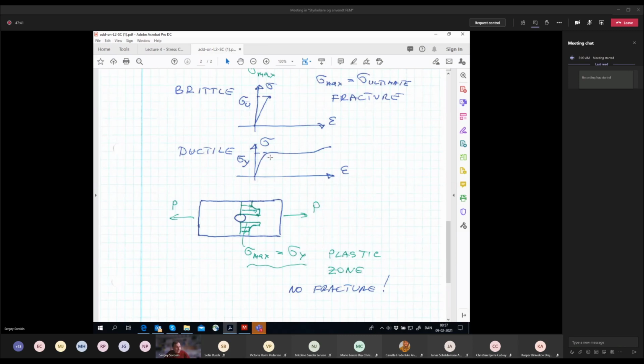If it's like this, then you have this kind of non-uniformness. You have this plastic zone confined by the surrounding elastic zone, so that the deformation of this specimen is confined. It's quite small. But if you have total plastic deformation across the cross-section, then you have very, very large deformation.